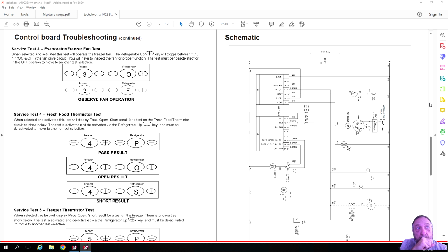Is it possible the manufacturer drew the diagram wrong? I have seen it. I do have a video on a GE stove where the manufacturer definitely drew a direct short between line 1 and neutral in their diagram, and I redrew it how it's wired. But that board should light up on 1 and 6 like you guys saw. So you could make a mistake.